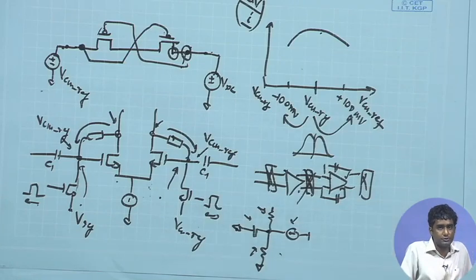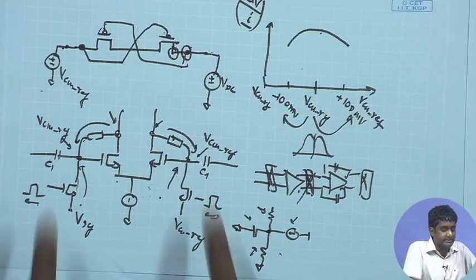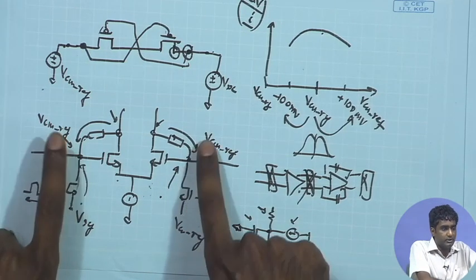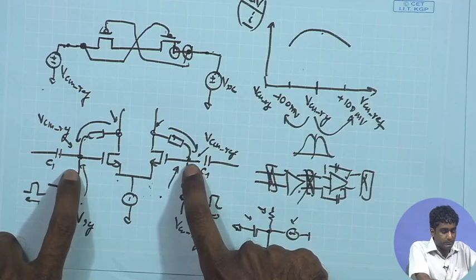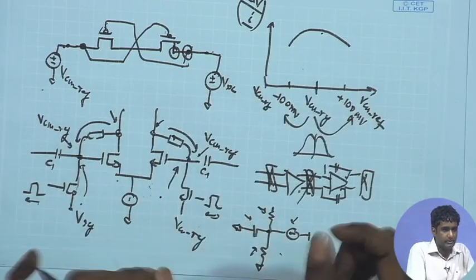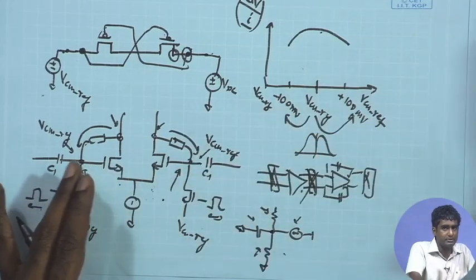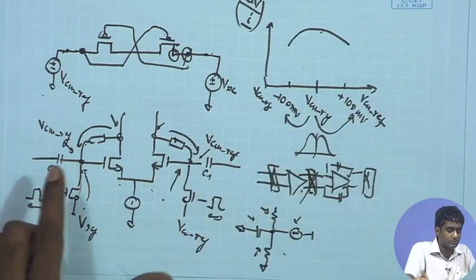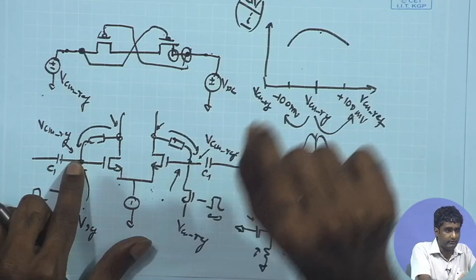So in the real circuit, of course, it will take, say, 1 second to settle this voltage to the required value. Likewise, in the simulation, to simulate that 1 second, it has to solve so many matrix equations depending upon your step size. So it will take many such matrix equations, and finally you will arrive at that 1 second point.